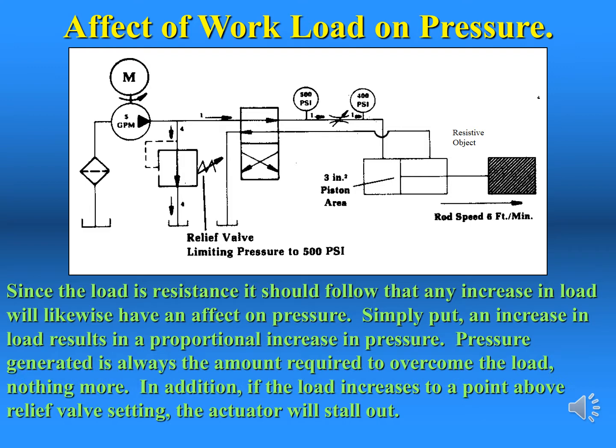As I mentioned before, the load on the actuator will also affect pressure differential. The more load applied, the more pressure is applied by the relief valve to overcome the load. If the load exceeds the potential of the relief valve, the cylinder stops. As the load increases, the flow going to the actuator decreases, sending the remaining flow over the relief valve back to tank. Students will get to see this when they use a device called the load sleeve during an experiment in the lab.